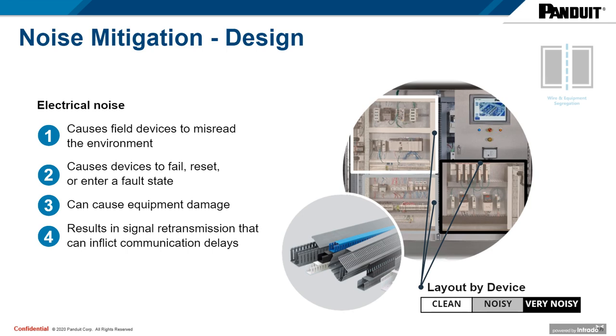Ultimately, this can be extremely expensive, taking the form of productivity losses, downtime, maintenance and repair costs, troubleshooting costs, device replacement costs, etc. These problems can be amplified by poor control panel layout practices, deficient grounding and bonding, and inadequate segregation of noise sources from susceptible devices and cabling.